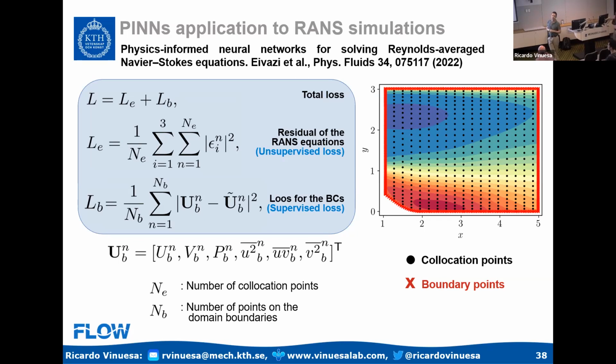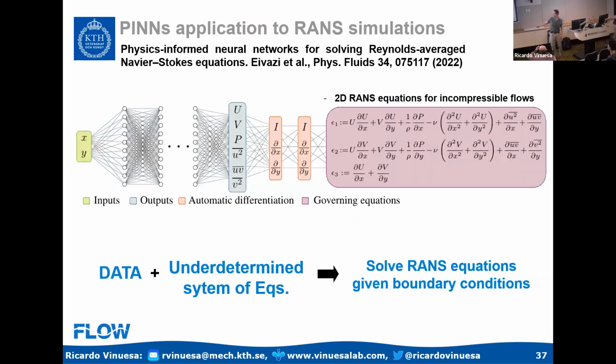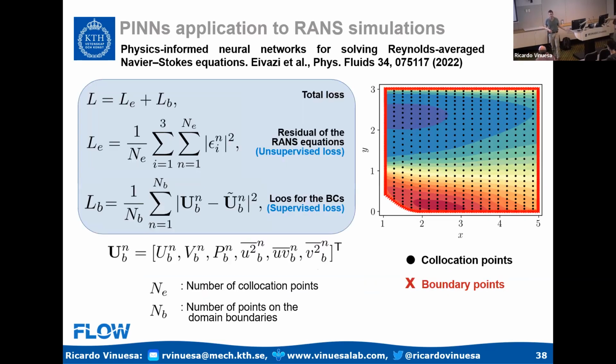The model comes from your boundary conditions as well. Exactly. Because if you want to solve the PDE, you need a model for Reynolds stresses, and that's where the error comes. We don't have that problem. Okay, but your boundary conditions cannot be on the surface, because that would be zero. That's okay. Let's say on a zero pressure gradient turbulent boundary layer, if you go all the way to the free stream, all those Reynolds stresses are zero. If you go to the wall, all those Reynolds stresses are zero. So you only have the inflow and the outflow. Yeah, so that we tried, and it actually works.